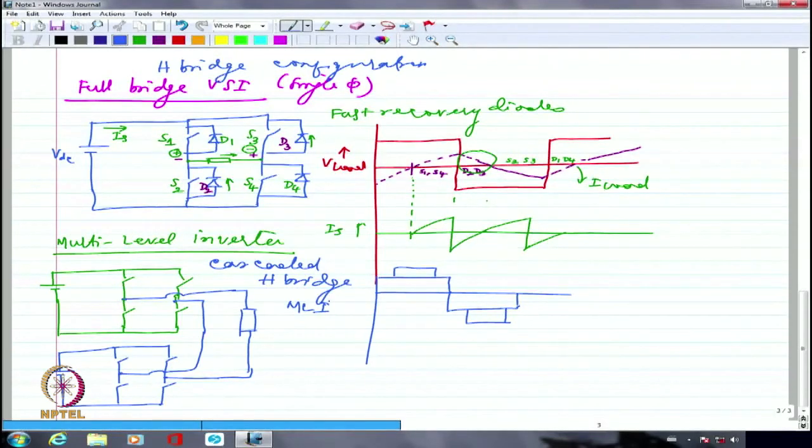Each of them can function independently as a single phase inverter, no doubt. So the major advantage I can visualize in this case is, if I have 5 such inverters connected in series, and one of them conks out, I need to essentially have in the inventory a number of the single phase inverter. Remove the faulty inverter, put the good inverter. You can do that. So it is like parallel operation of transformers, what we talked about earlier in the electromechanics course.